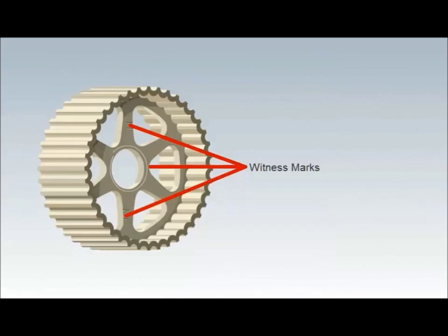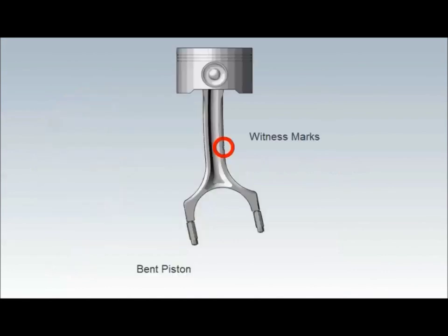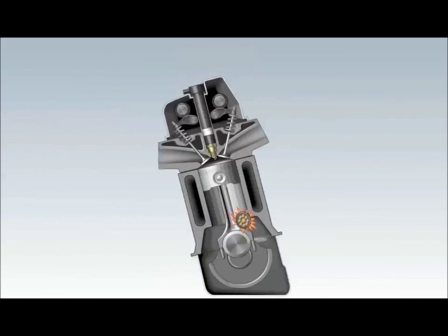Witness marks indicate contact between two parts. These marks may indicate normal wear, such as where bolts mounted the part, or pry points that occurred during disassembly. These are wear and tear witness marks and don't call for part replacement. However, witness marks can also indicate impact points that bent the part. Always identify the cause of these witness marks prior to completing the repair. The source of the witness marks that resulted in damage must be removed.